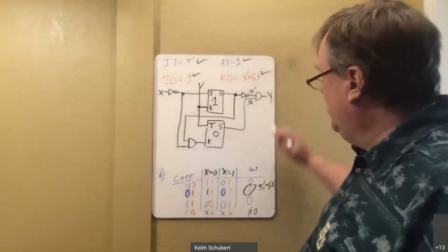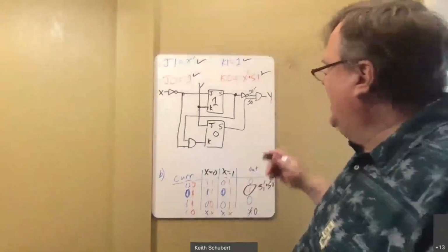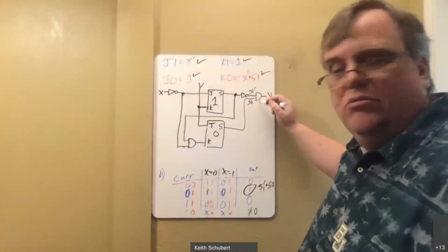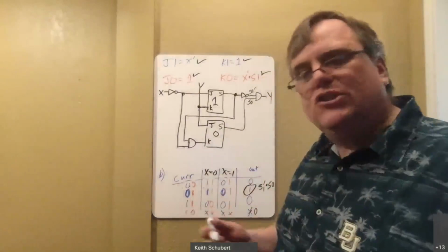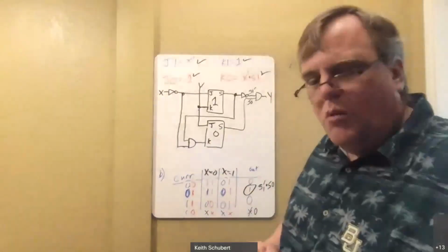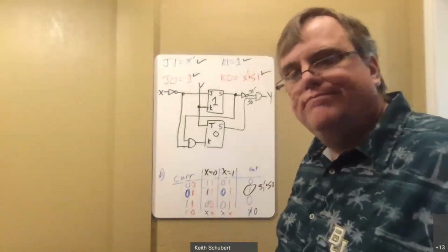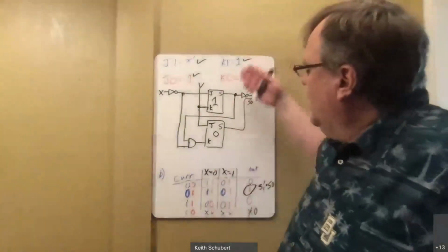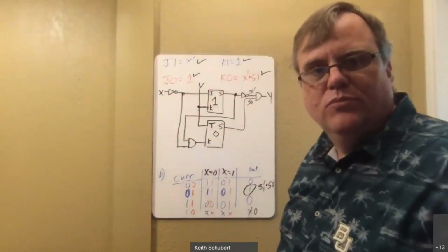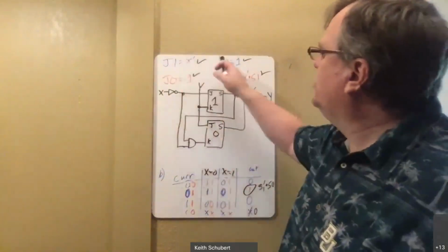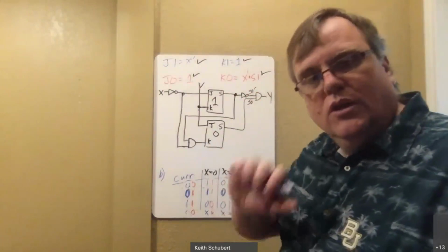I could have picked a 1 here, in which case this would become an XOR. But an XOR is slower, bigger than an AND gate. So since I don't really need it, why pick a big, slow gate? Pick a small, fast one. Small, fast, cheap. AND gates are nice and small and cheap. So that's why I picked it, but you could have done either. This gives you your circuit, which is the answer to 2C. So for 2C, you should show me these equations and draw me a picture that looks like this. You feel good?